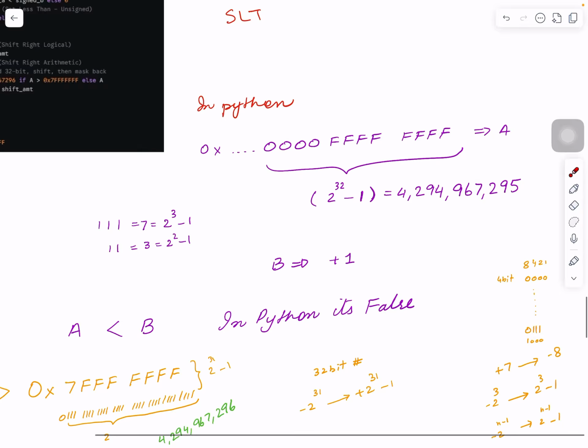Okay, I always look into this. Well, have a look at this. With 4 bits, you will have numbers from plus 7 to -8. These are 16 numbers because this is a signed number, right? So if the most significant bit is 1, that is the most negative, -8. And if this is 0 and the rest of them are 1, this becomes plus 7.